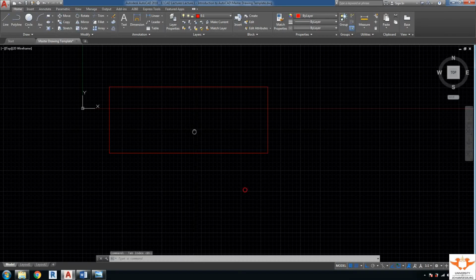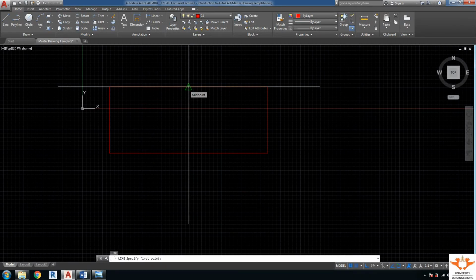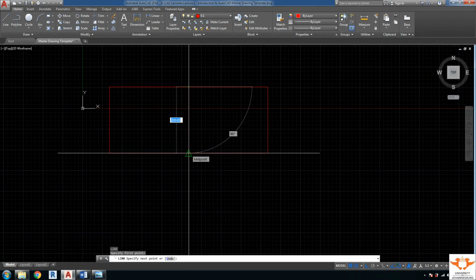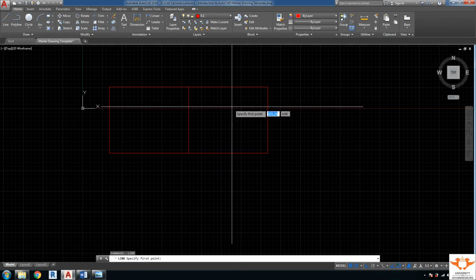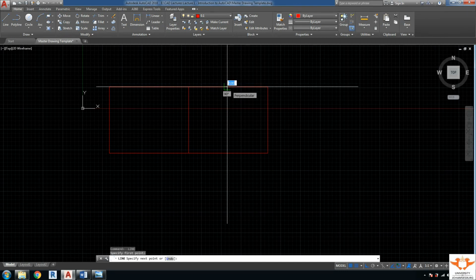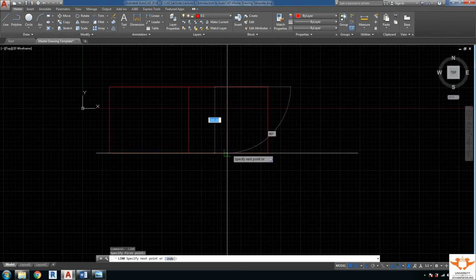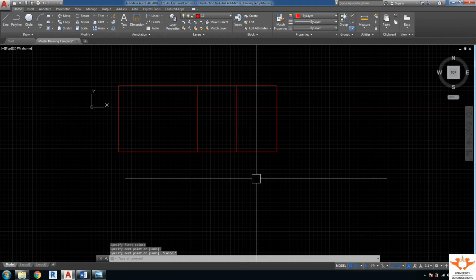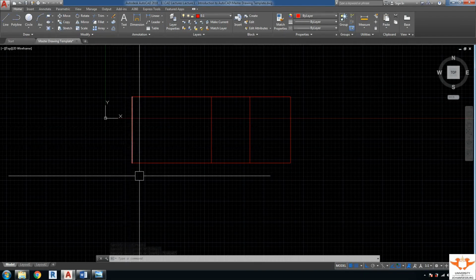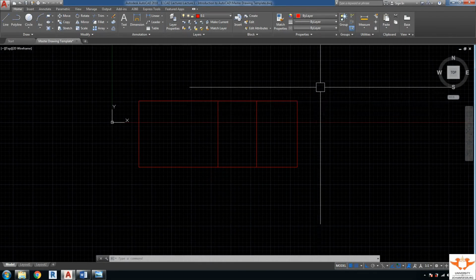Yes, it does click to the midpoint, bring it down to the midpoint again. If you were to draw it off the midpoint, you'll find that the perpendicular sign comes up to say it's perpendicular, and perpendicular again, and that's how we use the snaps to guide us when we're drawing in AutoCAD.